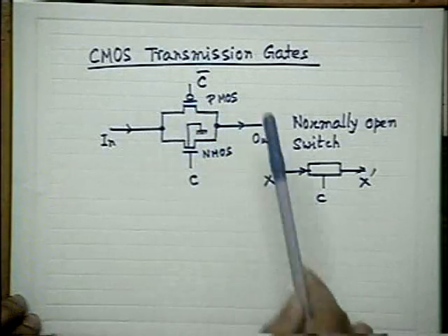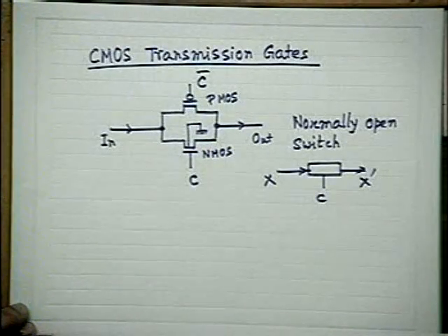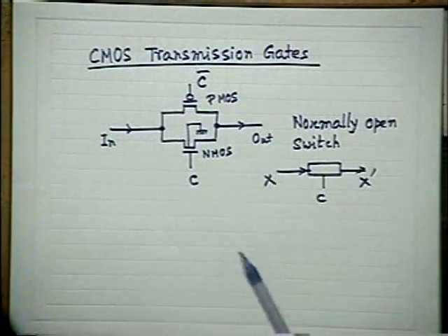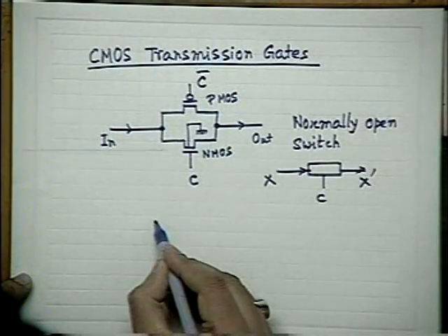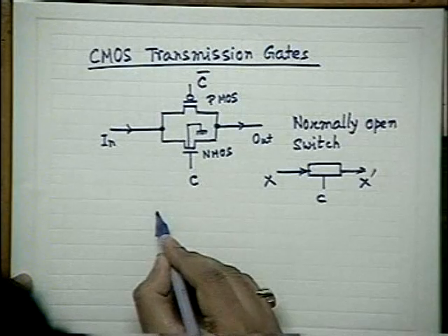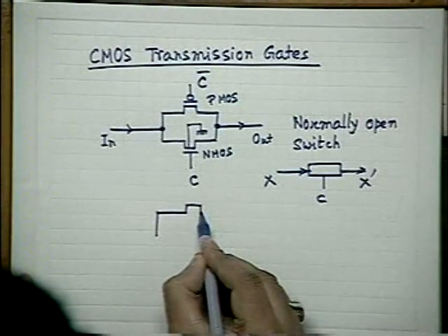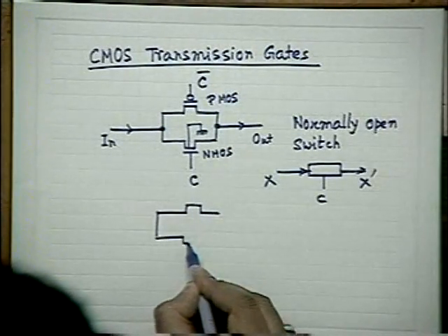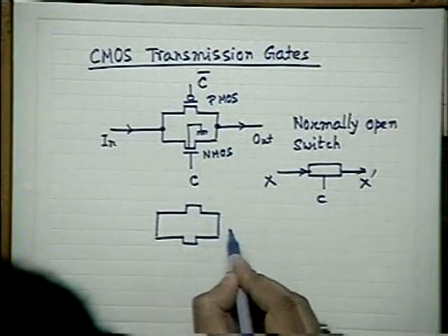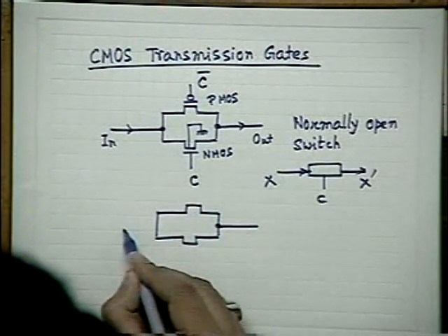If you use a single channel inverter, firstly, using PMOS, you have to use a negative logic. This is a problem. You have to use a negative logic. And secondly, using nMOS, combining PMOS with nMOS, only then can you get this advantage, not in the other fashion. You can easily see what will happen for the other switch. It's the same thing, but only depending on the application of the clock.